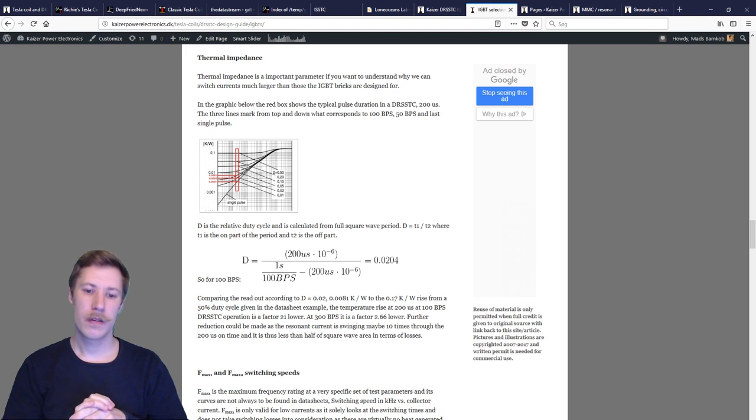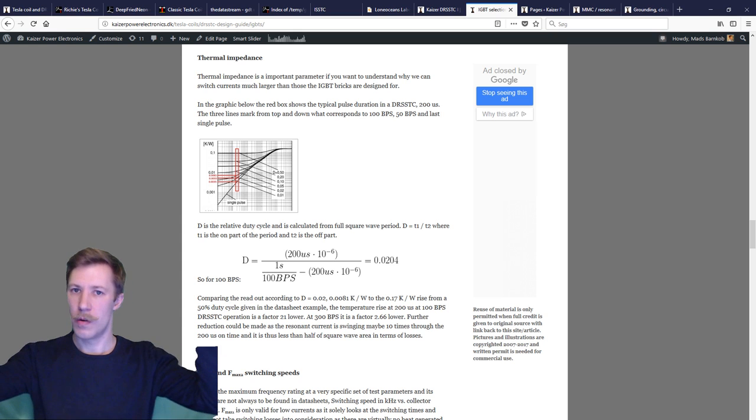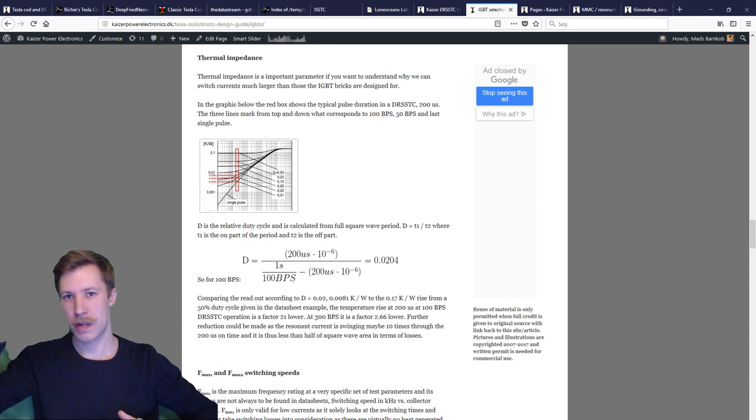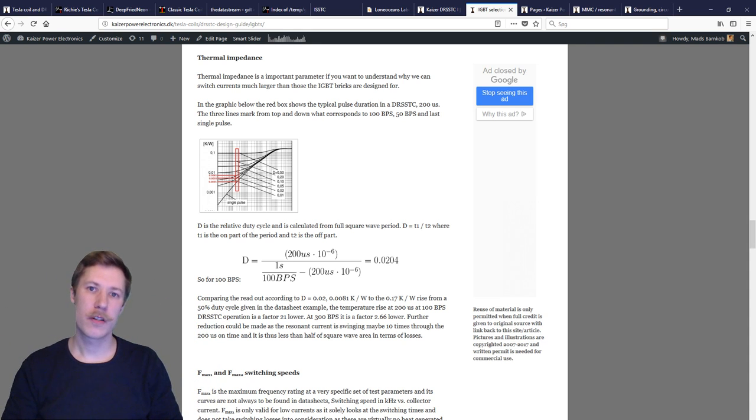You must be sure that you do not supply your bridge at one end, so you have a higher peak current at the top IGBTs, but you must supply it crossing everywhere to ensure that you have even current path everywhere that it is possible.